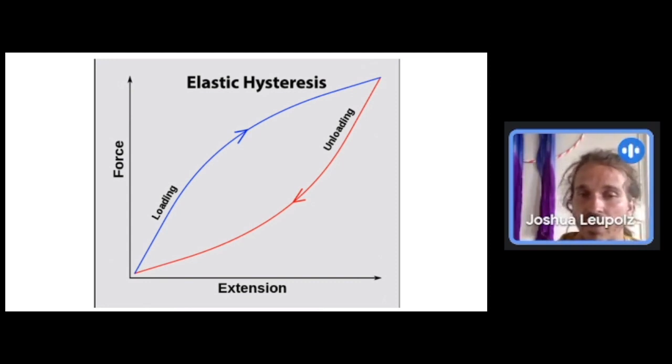And I think it's also not too hard to do. You just need a camera filming the webbing, how much it is stretching out. You need a load cell over time, getting the chart out of it, and then just matching it up and measuring it. And then the same thing for backup falls: having a webbing relaxed, making 2 marks on it, and then relatively fast loading it. That might be technologically difficult, to really stretch your webbing from 0 to 5 kilonewton within 1 second.